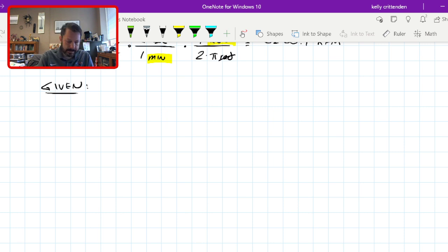What are we trying to figure out? Determine how much horsepower. We know the size of it, 7-inch diameter. This is a massive shaft. It doesn't say anything about an inner diameter, so we're assuming it's a solid piece. It doesn't say what material. They just give us the tau allowable equal to 11,500. So based on that number, that is some kind of steel with a factor of safety applied to it. So this is a really big steel shaft spinning 190 RPM.